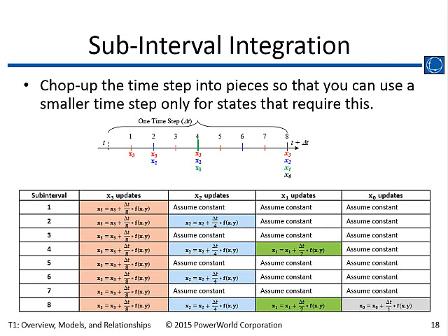On, let's say, one exciter that has 5 differential equations, we realize that we need to use 1/64th of the quarter cycle time step. So we will internally modify the time step, but just for that single exciter. So we run 1/64th times 1/240, a very small time step. If we did that for the whole system, it would take forever to solve. So we just do particular models.